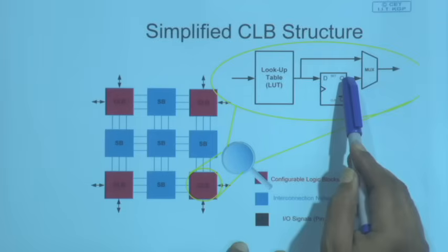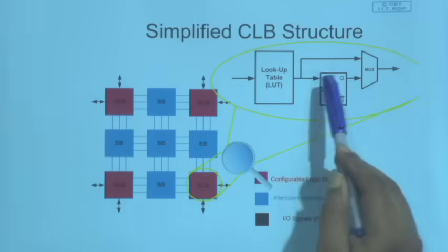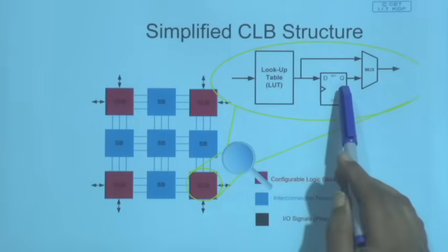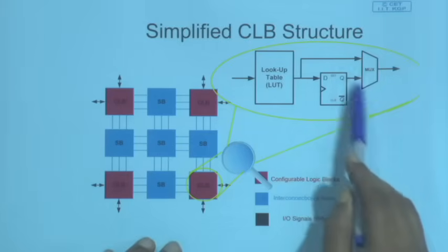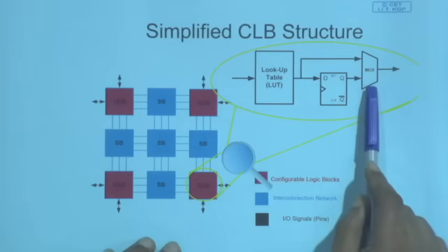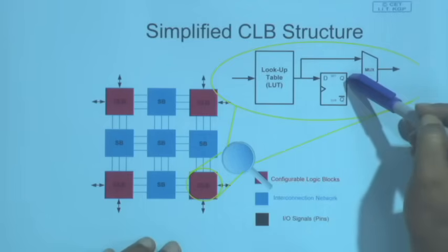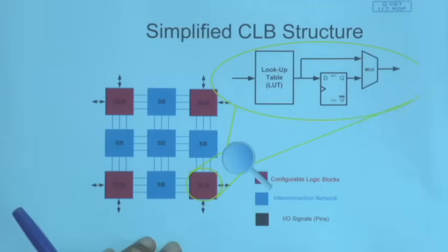And all of you know that the D flip flop will have whatever is the input now made available at the output after 1 clock delay. So, I can establish a delay by this. And I can activate the control of this multiplexer to either select this input or select this input, any one of them can come, all right. Is it clear?